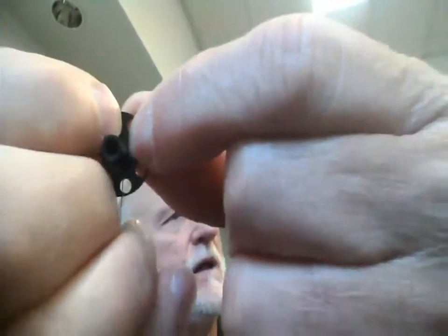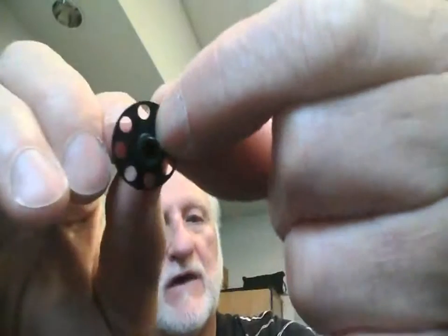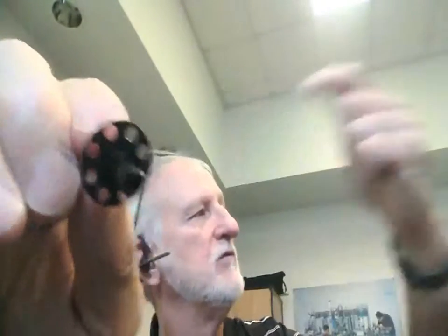When I started off, every time this one was on a light one, the other one would be on the black. And of course, if I spun it one way, then one of them would pulse before the other one. If I spun it the other way, then the other one would pulse first. And then I could use whichever one pulsed first to indicate what direction.